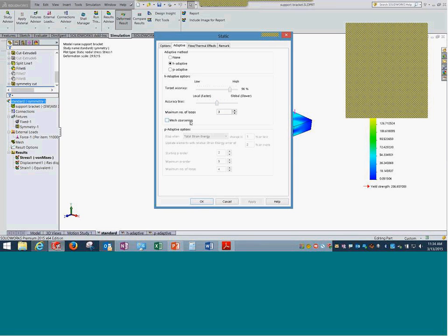And this cannot go on infinitely. It loops a certain number of times only, and we can control it. Here we have 5 loops maximum, so it will try 5 different times to find the mesh, and then it can stop. After the 5 loops are done, we can check the results.